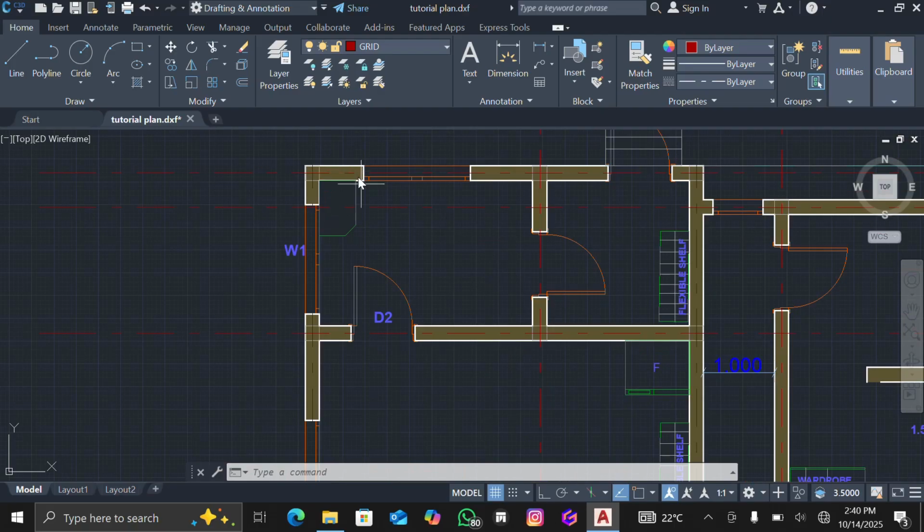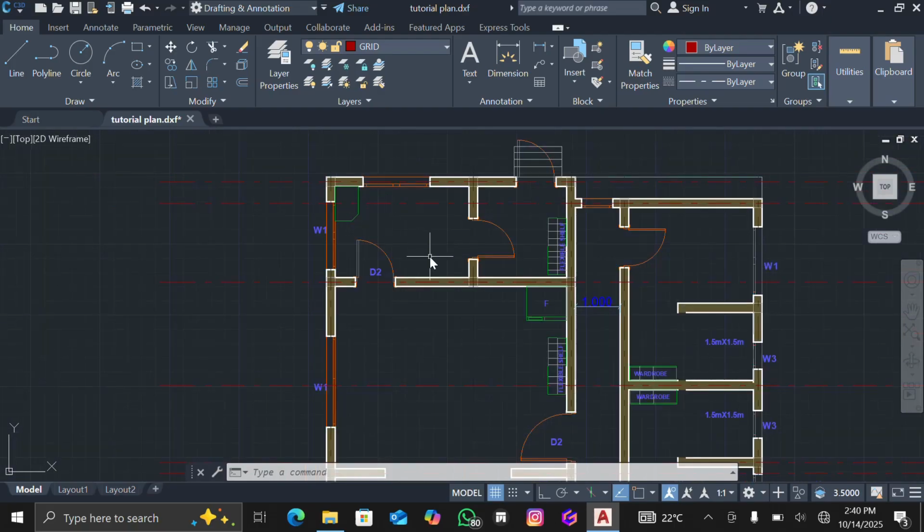Now on inserting the columns, there are some fundamental principles that we follow, that you are supposed to understand as a structural engineer. There are many principles that you have to follow. One, the distance from one column to the next shouldn't exceed 6 meters. That is by the codes of practice. You understand? It should be 6 meters and below. The permissible one is 6, that is the maximum. That is one of them.